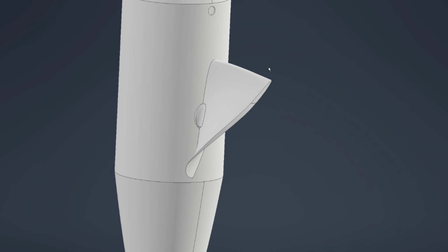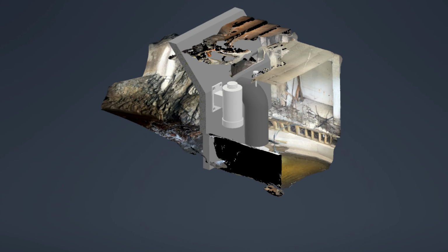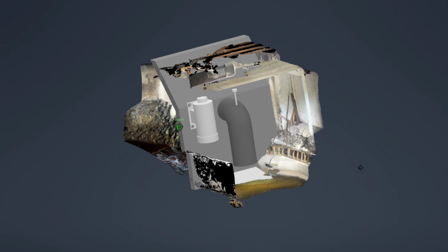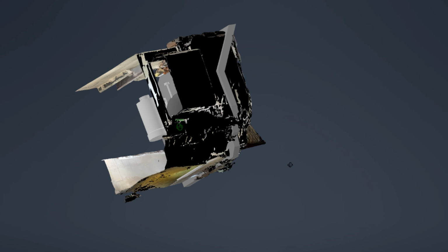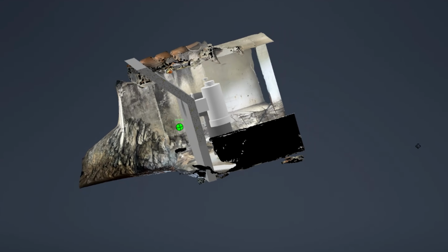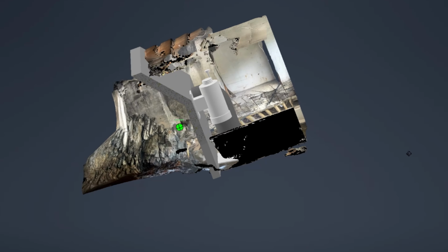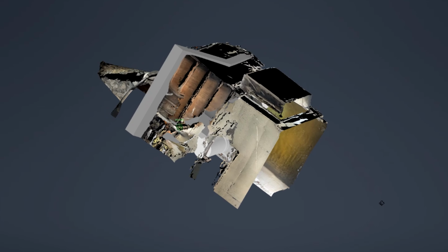Job 2, the fine trim. The angle of attack itself, you see the bite that the blade actually takes out of the fluid, has a small, roughly 2 to 5 degrees of freedom. More attack means more lift and more torque. Less attack means the opposite. So as the grid frequency drifts with load, we have a mechanical governor that will just gently tap the pitch to gently follow the 50 Hz frequency.